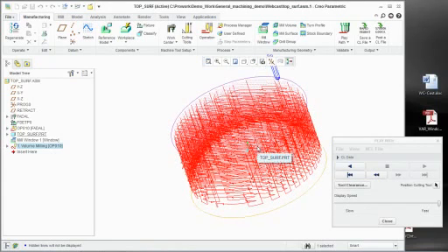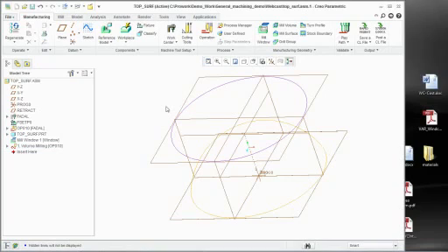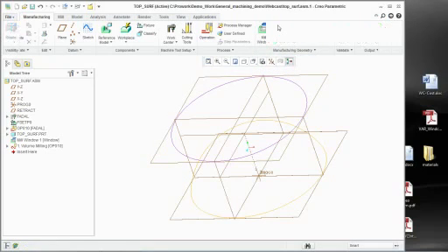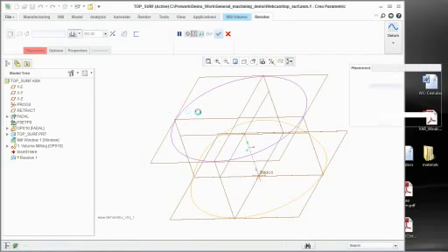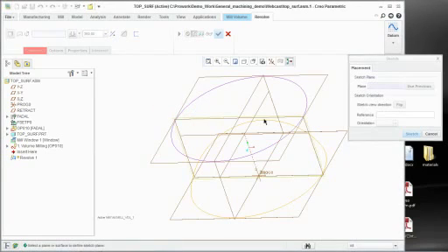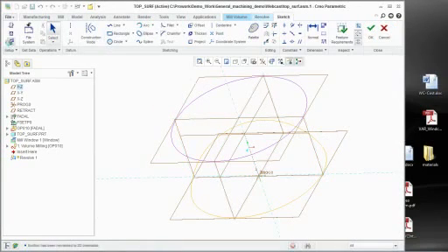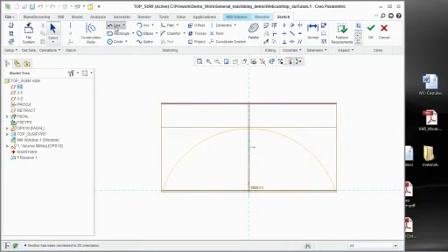And if you were machining out a big giant block, this is perfectly fine, but not everybody does that, okay? So what you have the ability to do in a voluming toolpath is conform your shape, or the top shape of your toolpath, to the shape of what would be something called a mill volume. Okay, and what I'm going to do in the mill volume is I'm just going to come in and create, in this case, a fairly rudimentary shape that emulates what my casting would be. So I'm just going to come in and say, this is what essentially my casting would actually look like.